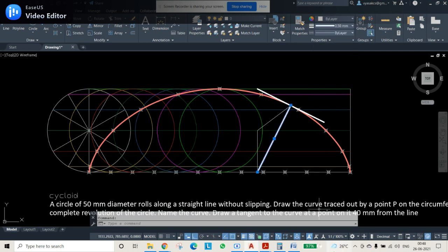Even if the question only asks for the tangent, without getting the normal you can't get the tangent in this case. So how did we draw it? We have taken the point by the given information, and from that point we have drawn a circle with the radius of the question. After that, we draw a straight line up to the bottom straight line, which is drawn with 157 mm. From there, if you draw to the point taken, that becomes the normal, and perpendicular to that normal, whatever the line is, that becomes your tangent. So this is your tangent and this is your normal.